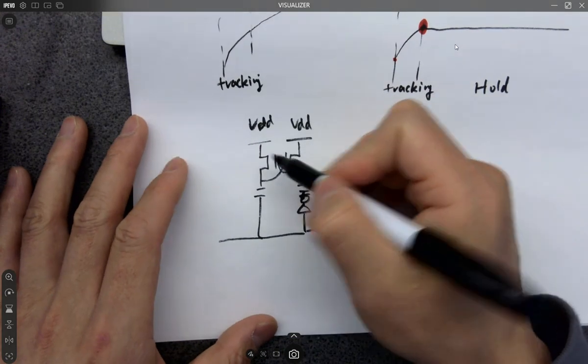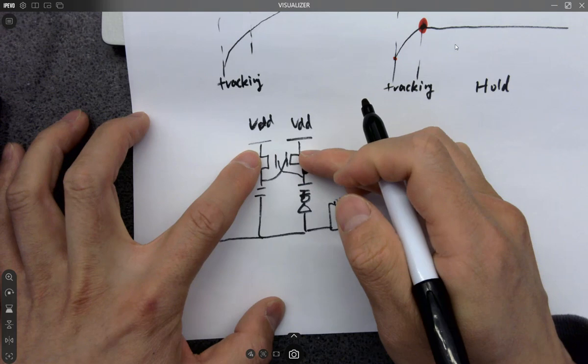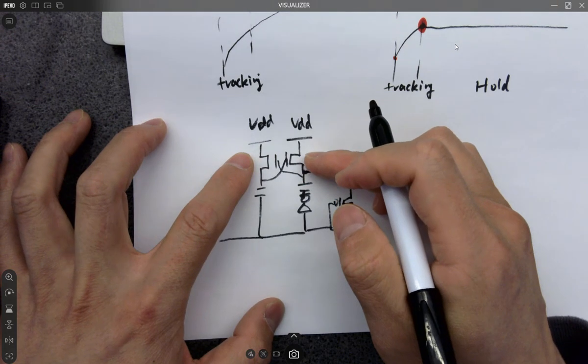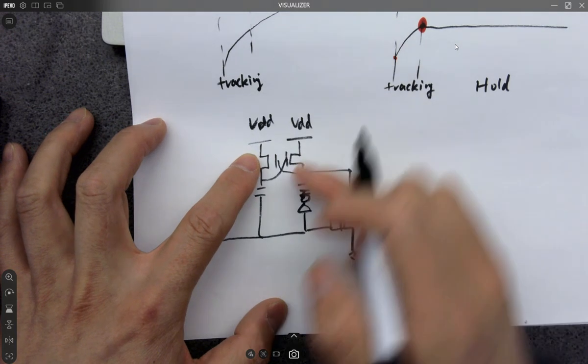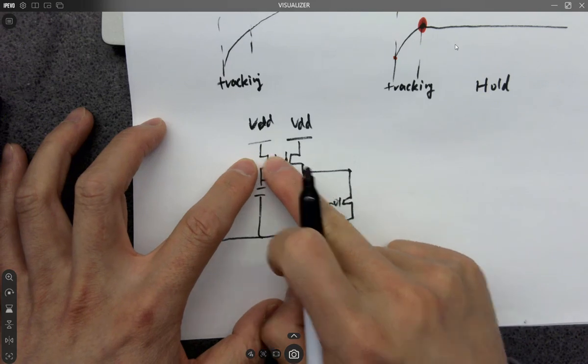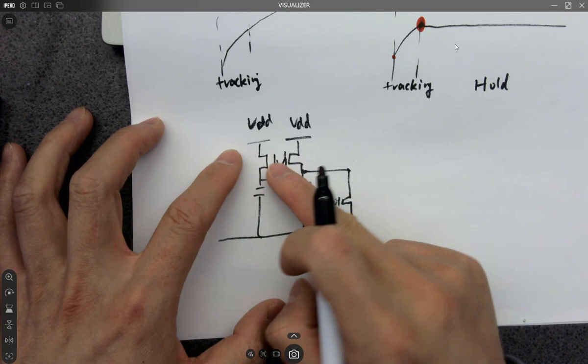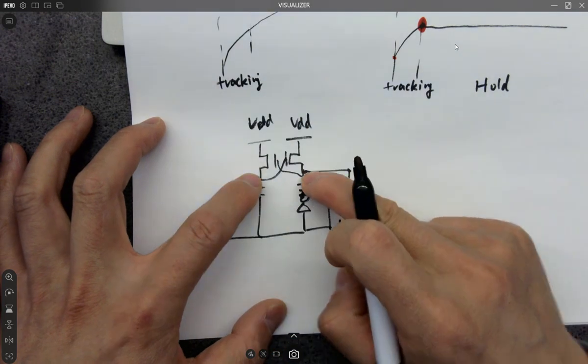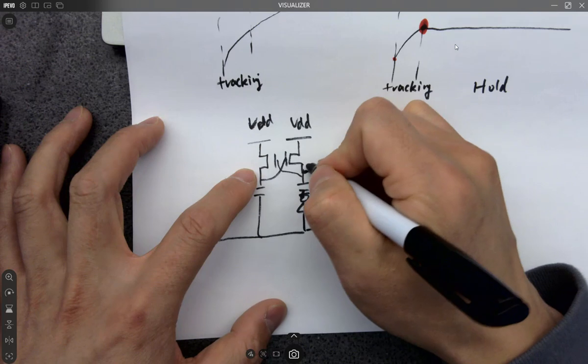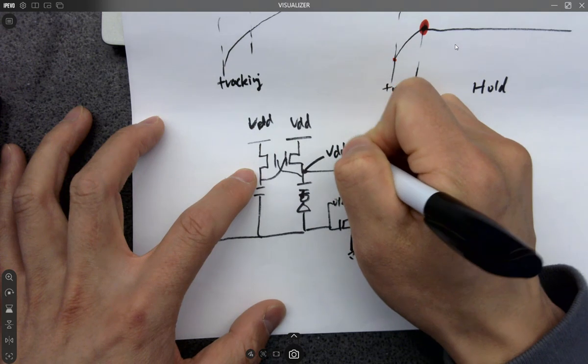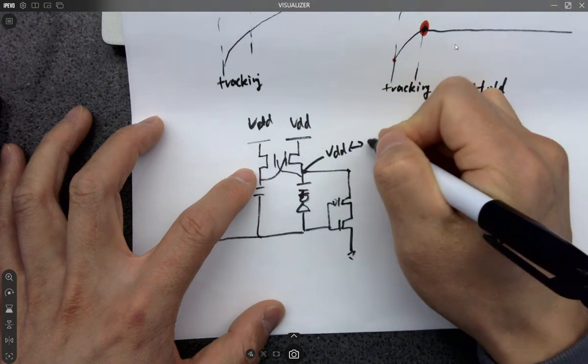Because in the first cycle, the NMOSes are still losing one VTHN, but after the first cycle, both of the VGs are getting a value which is larger than VDD, so eventually it's able to pull the entire VDD to these two points. So eventually this point is going to oscillate from VDD to VDD.